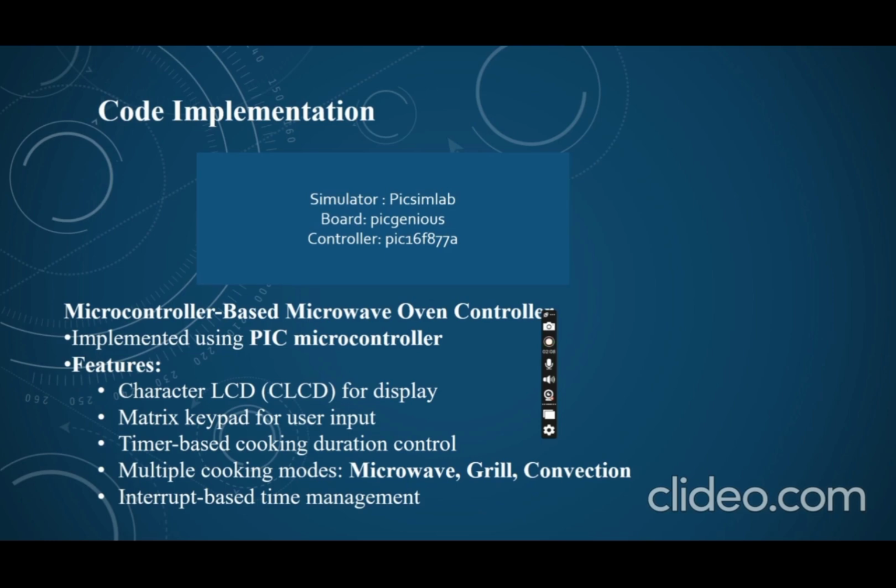We also use an interrupt service routine, ISR.c, which handles timer 2 interrupts to manage time-dependent features like countdown timers for cooking and preheating. As for the operational flow, as I already said, upon powering on, the power on screen function displays a welcome message and menu navigation.